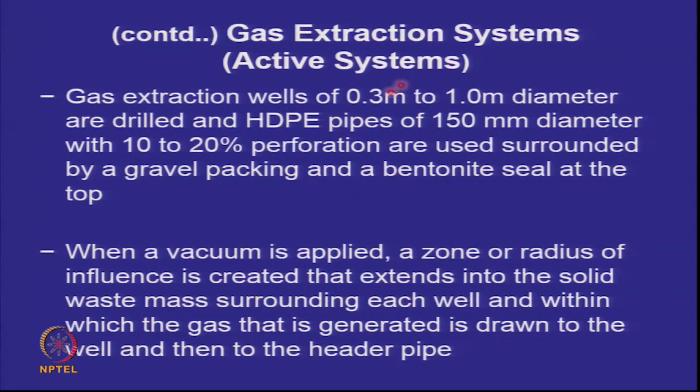Typically the wells that we use are 1 foot to 3 feet in diameter, and these are HDPE pipes because you don't want the waste to interact with the other pipes. So you make a well, and in that you keep a smaller diameter perforated pipe with 10 to 20% perforations and surrounded by gravel packing.